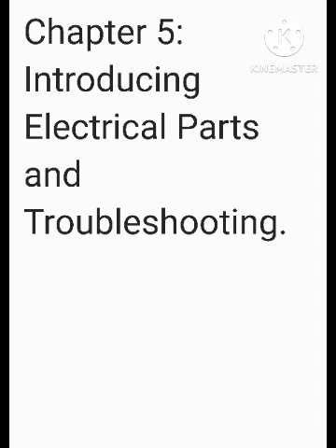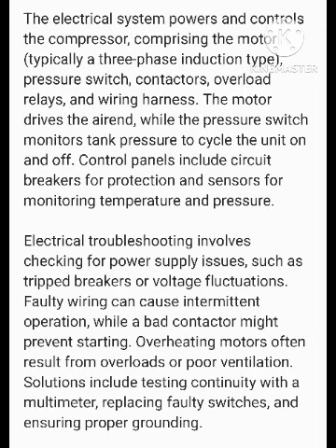Chapter 5: Introducing Electrical Parts and Troubleshooting. The electrical system powers and controls the compressor, comprising the motor, typically a three-phase induction type, pressure switch, contactors, overload relays, and wiring harness. The motor drives the air end, while the pressure switch monitors tank pressure to cycle the unit on and off. Control panels include circuit breakers for protection and sensors for monitoring temperature and pressure.